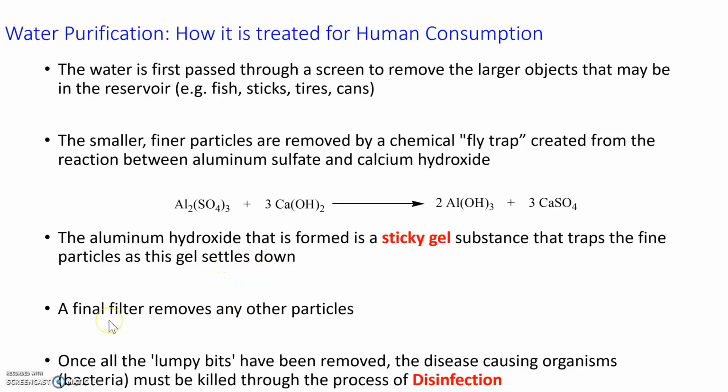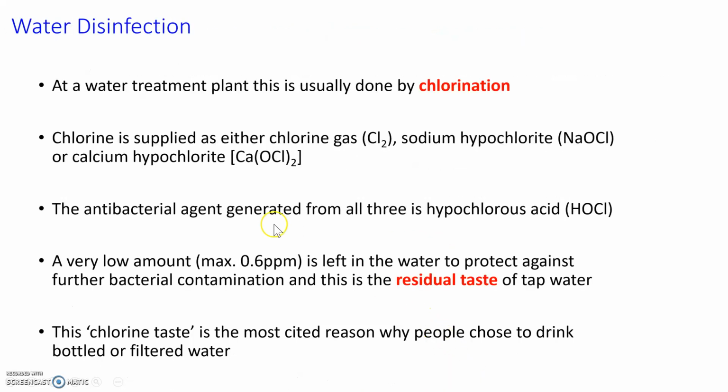Once you've removed those particles, the water passes through some type of filtration unit to remove anything else that is left in the water. And then the last step is disinfection. So these steps remove particles, but cannot remove bacteria. That bacteria can cause issues.